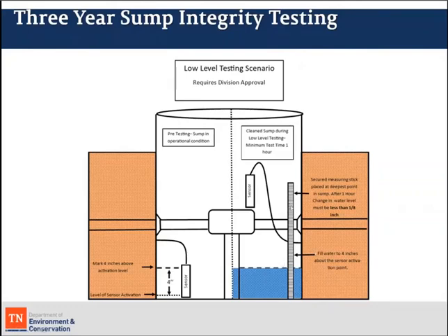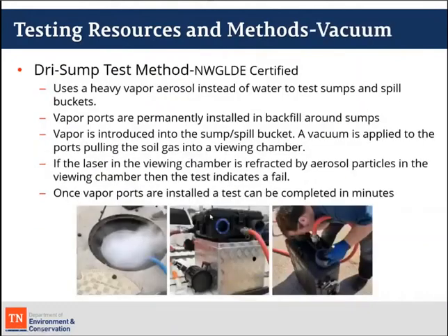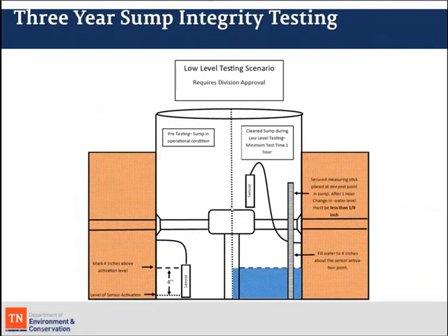And then, obviously after you're done with all these test procedures, you want to return the sump back to its normal condition. As David alluded to earlier, especially in your normal test scenarios where you're covering up all of these penetration points, you're going to want to loosen any bands that you've tightened around maybe the outer wall of piping coming in.